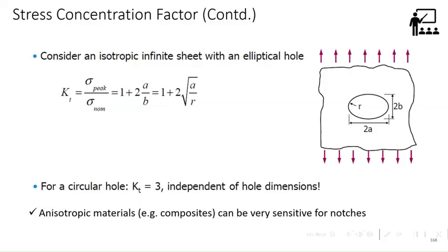A lot of fragments of fiber and all will be there, so it raises the local stresses. KT is more means local stress is very high. To reduce that, use a water jet. But unless you close that surface, there will still be cut edges, right? So that's why it is high.